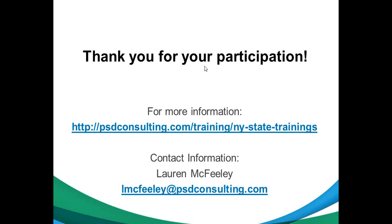Correcting those kinds of sensors and things like that in the field are more under retrocommissioning. And retrocommissioning is more of a process where you're testing, does an individual piece of equipment function the way it was designed to function, taking it through a whole series of tests. And it's typically done in the field. And to me, that's more of a micro picture. You're looking at one piece of equipment at a time.